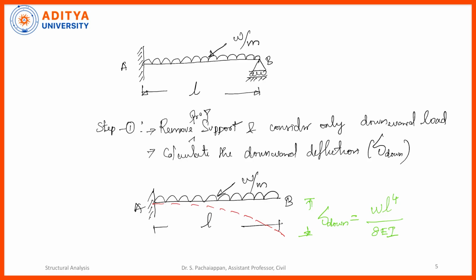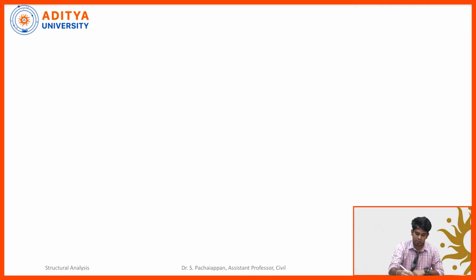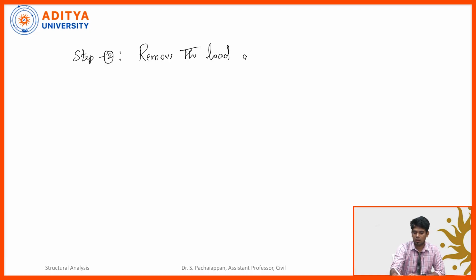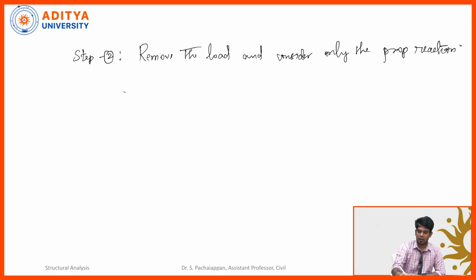Go to the procedure, step 2. In step 2, we are going to remove the load and consider only the prop reaction, and calculate the upward deflection.